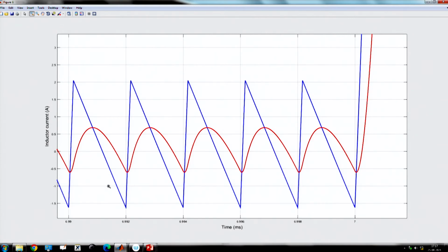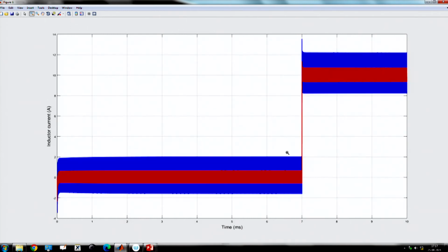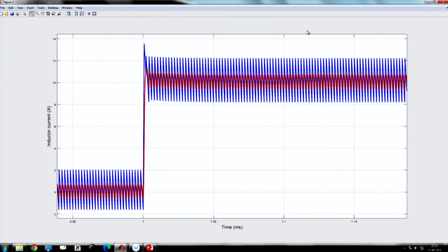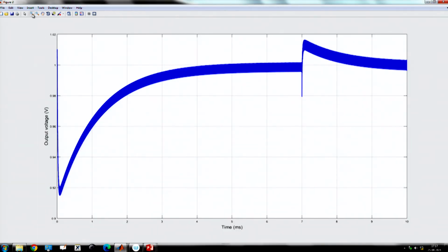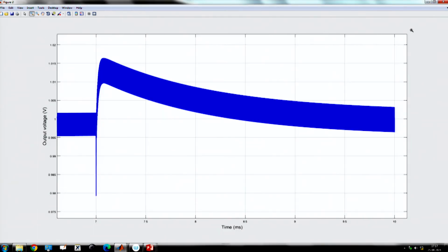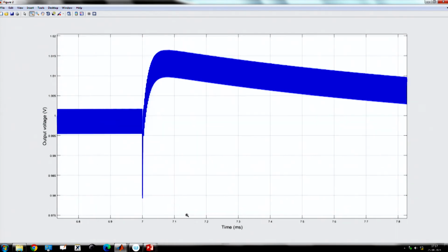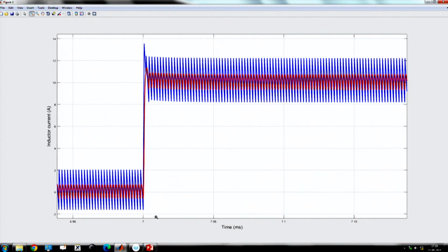We still have not extracted the average current, because it is set to 1/10 of the switching frequency, right, and now there is a load step change, okay, and you can see the output voltage is now getting regulated, because the current loop has an integral action also, though we have not connected any closed outer voltage loop, okay, because the current is trying to maintain the desired reference value. Earlier, since we had considered only proportional gain in the current loop, the output voltage regulation was affected.